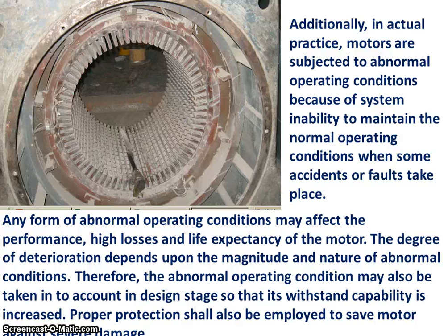The degree of deterioration depends upon the magnitude and nature of the abnormal conditions. Therefore, abnormal operating conditions may also be taken into account in the design stage so that the withstand capability is increased. Proper protection will also be employed to save the motor against severe damage.